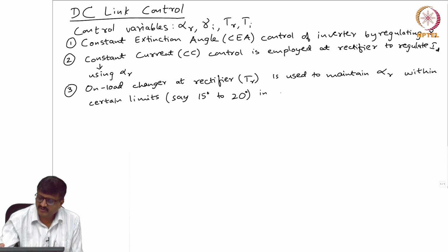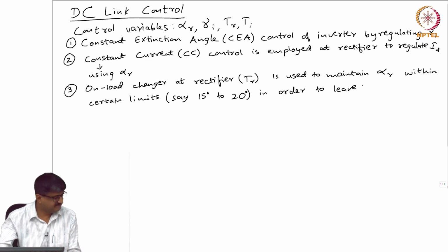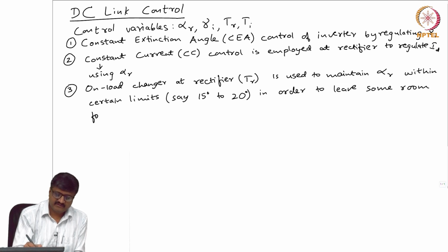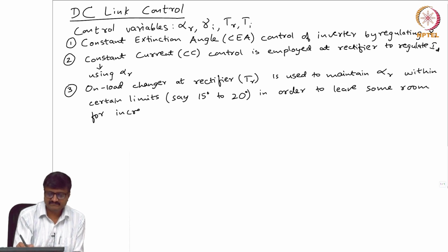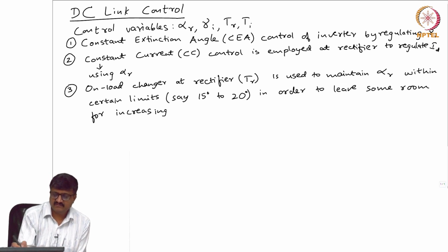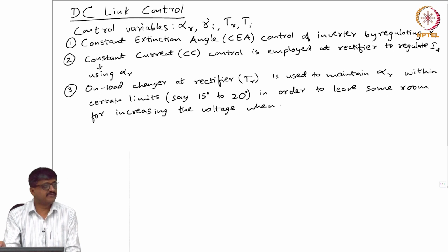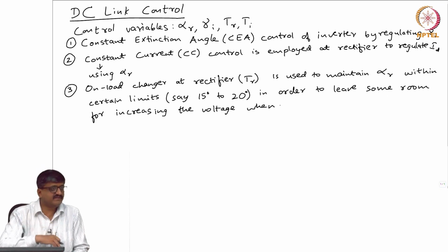This is done in order to leave some margin for increasing the voltage, when the AC system voltage for some reason comes down.